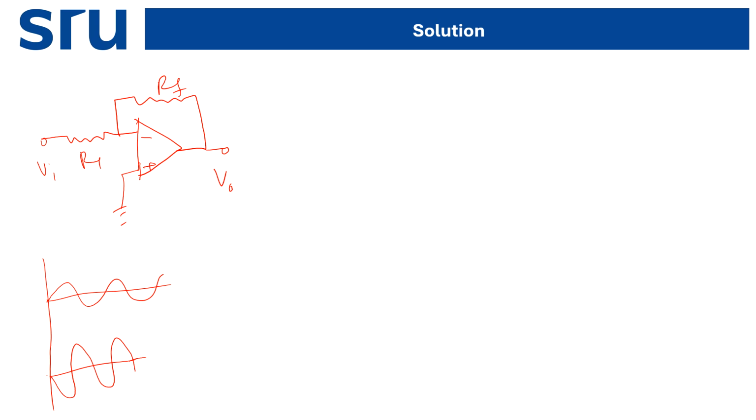As you know, this is the typical performance of an integrator using an op-amp. So the mistake the fabrication team might have made is that by mistake they put a capacitor in place of the resistor in the feedback loop.